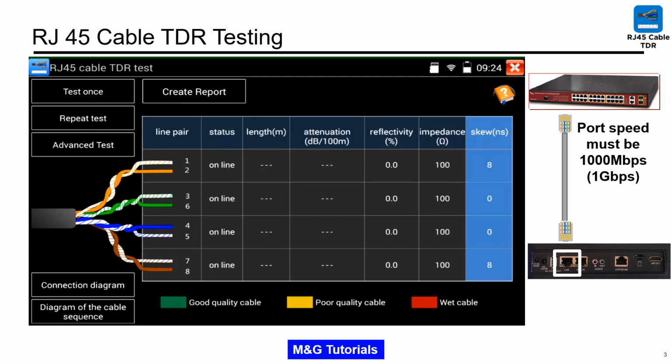Impedance is DC resistance. The tester does a loop test. All pairs should be the same. If you don't get the same on all pairs, you either have poor connections, different types of cable, or damp within the cable. Expect a reading between 85 and 135 ohms.